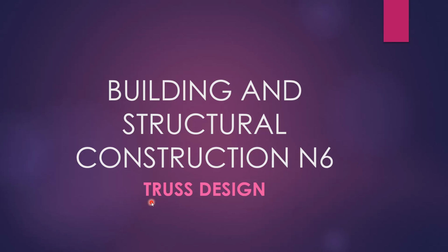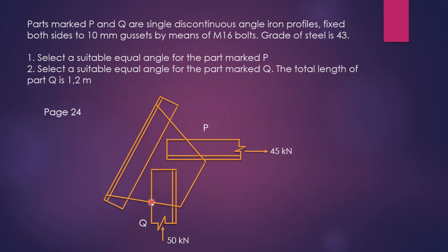So, designing a truss. What is truss design? Truss design is where we want to determine the members which will be able to carry the load. We want to select the members from the steel table which will be able to support this load. This is what we did in N5, N3 and N2, where we calculated these forces and also the nature.